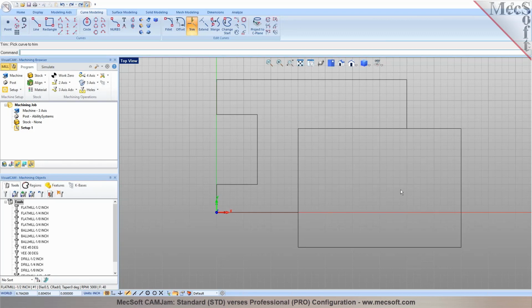Now, what does the command recall do? It means it keeps the command in the loop. Basically the command stays active. Oh, okay, I got you. So you don't have to go back and click on trim each time. It stays in a loop, and you can hit Escape to cancel out of the command.